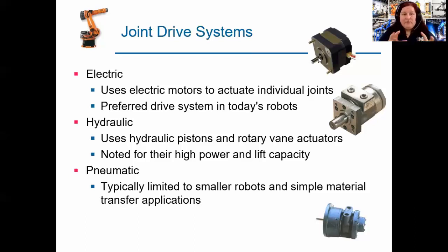But if we want to do something on a precise location and we're changing location throughout the time, maybe electrical will be the preferred way to go. So you will see hydraulic might be slow, pneumatic fast, electric in between. But in terms of forces, in terms of the environment, we have all these things that we have to worry about when we want to decide which one of these we would go with.